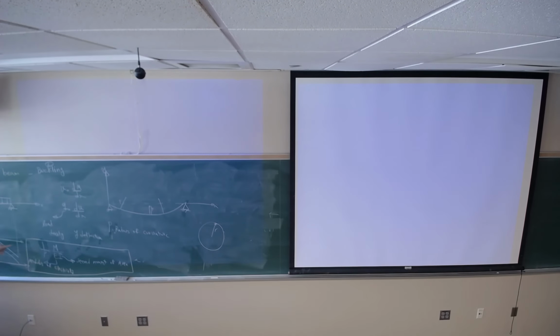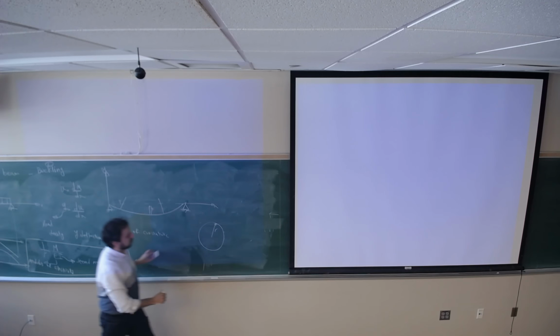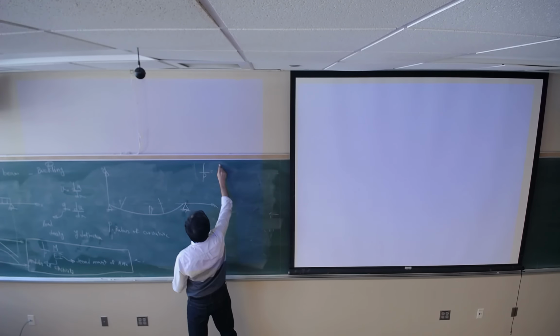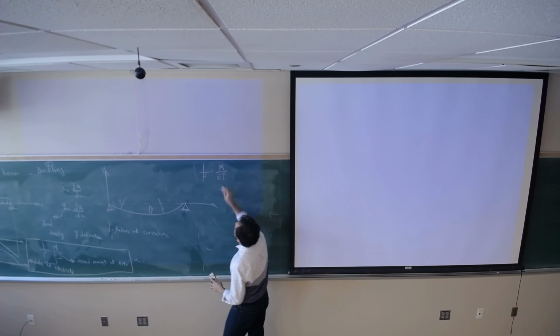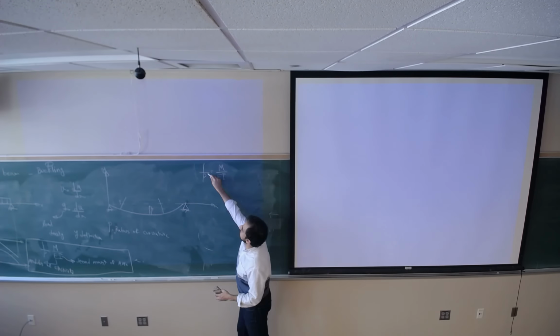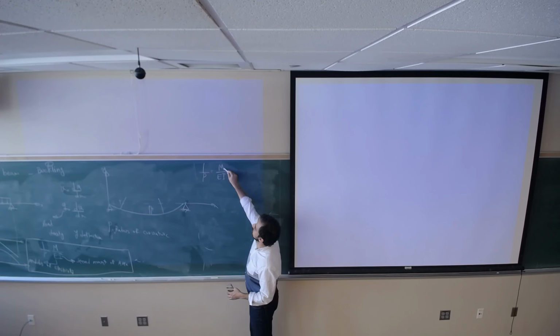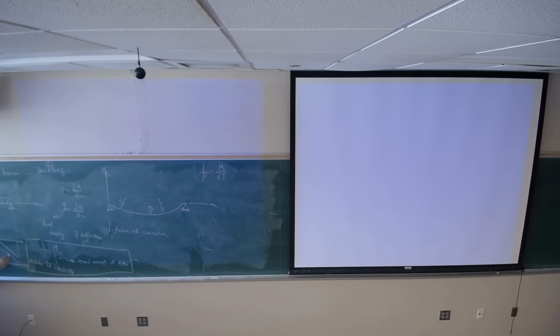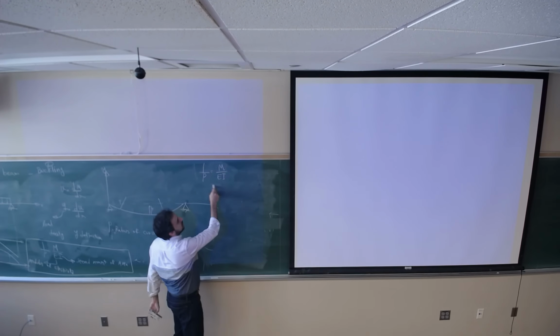One over rho is going to be M over EI. So at any point, if I ask you to find the radius of curvature, you should find the bending moment, which is coming from this graph, divided by E, the modulus of elasticity of the material.